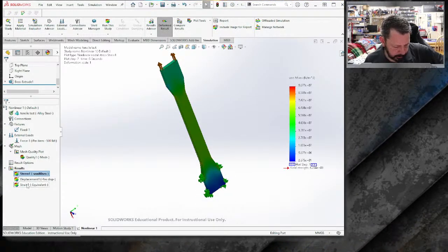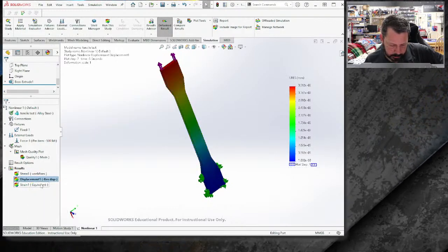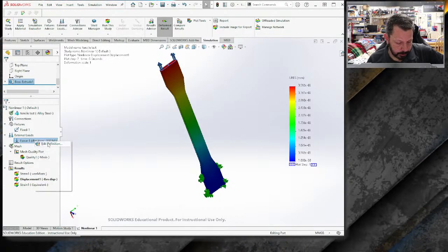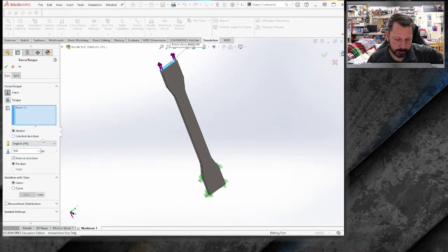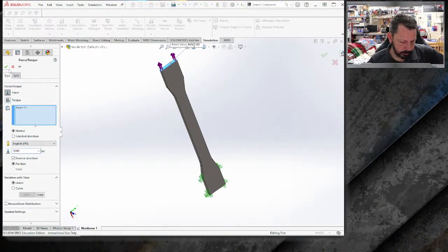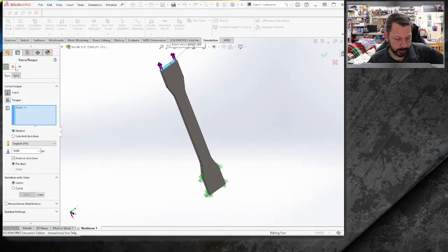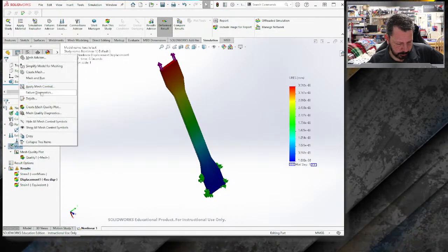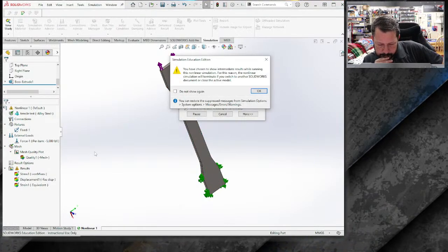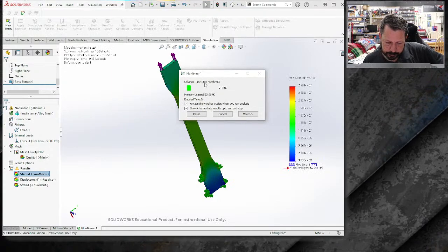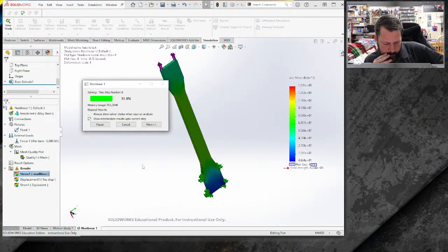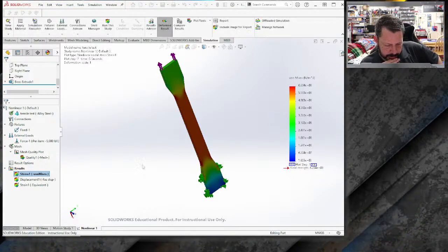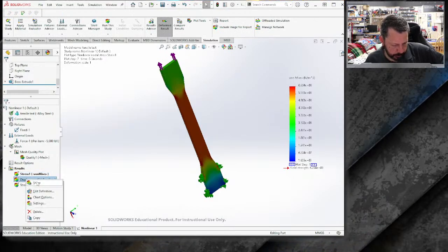And let's look at our displacement. Doesn't look like it, we might need more force. Actually, you know what? Let's try a larger force. But we might need to actually do what I wanted to do originally, which was to apply an actual displacement. Let's make this 5,000. The problem with this could be that it will break, and then the simulation will kind of fail. But let's just try. Let's do mesh and run. Yes, don't show that again. It keeps deciding to just do 7 steps though. I'm not sure why. That'll be in our properties.